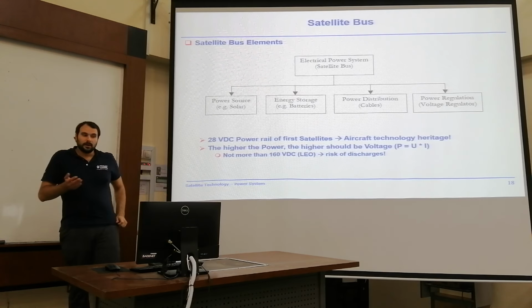Those are the two concepts I just want to show you with this plot. And just have a last look before I move on, how many different voltages we have here on the satellite. This is a relatively small satellite, like a refrigerator. 17, 20, 15, 12, 10, 5, 3.3 volts, minus 5, minus 30. So those are a lot of voltages.